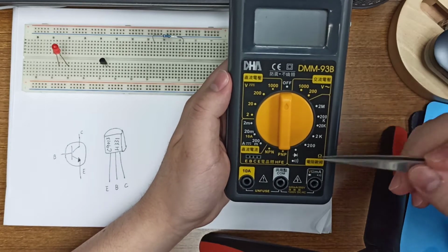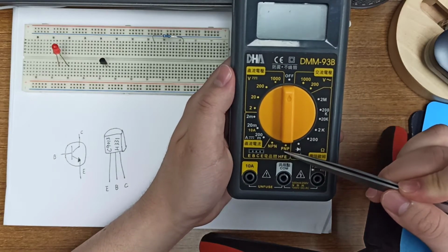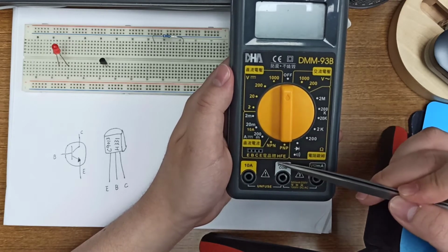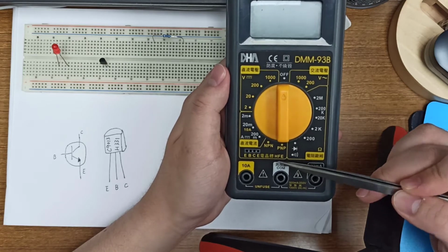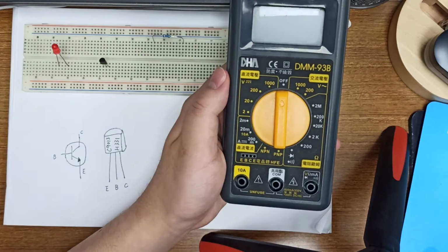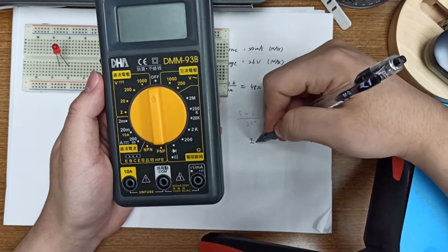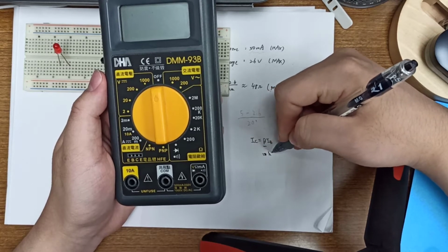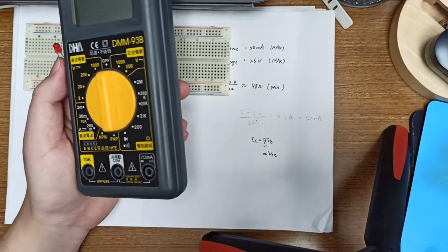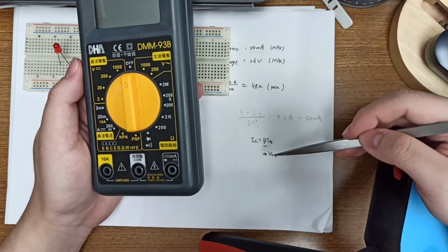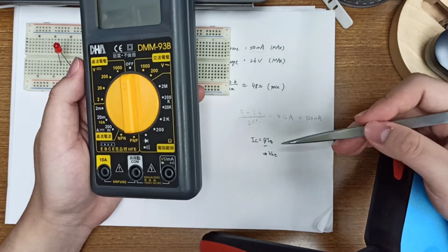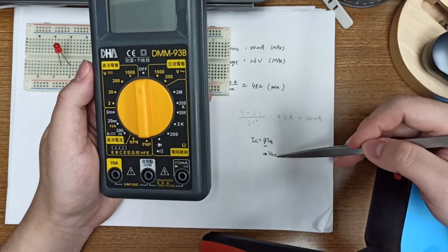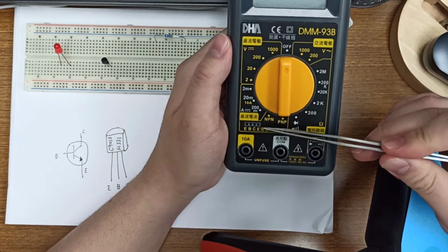And the next part is the HFE of the transistor. You see the NPN and PNP. We can measure the HFE of the transistor. The HFE is also known as the beta. You have learned in electric circuits that IC equals beta times IB. In some data sheets, the beta is called the HFE. So when you calculate the DC analysis of a common amplifier or some transistor circuit, you need to know the beta. The beta is HFE, and you can use the multimeter to check it.